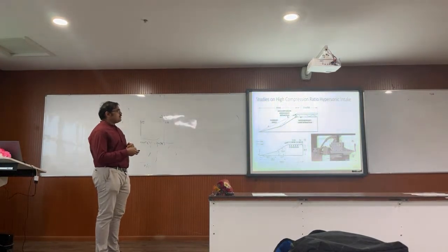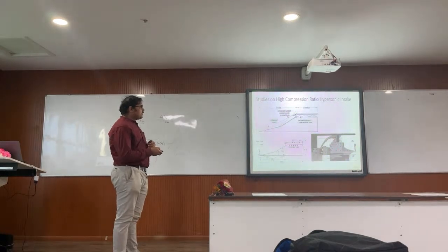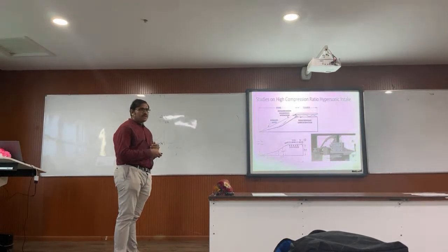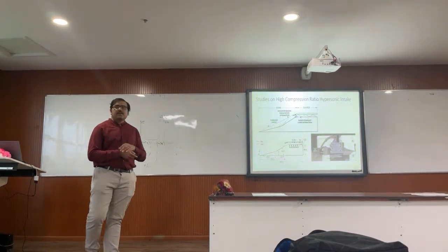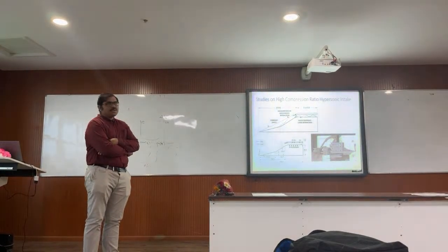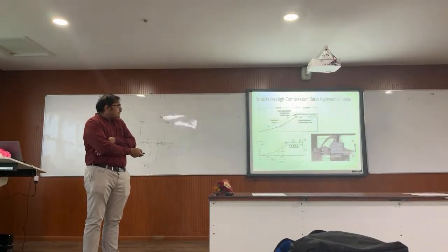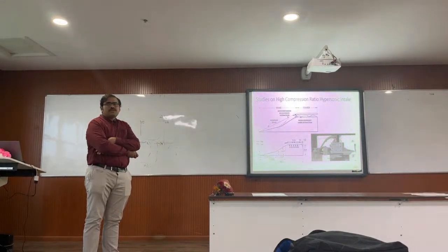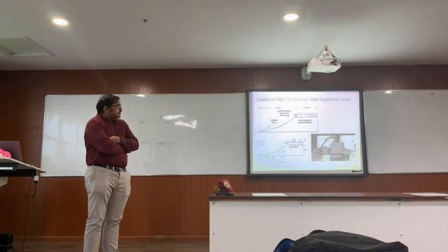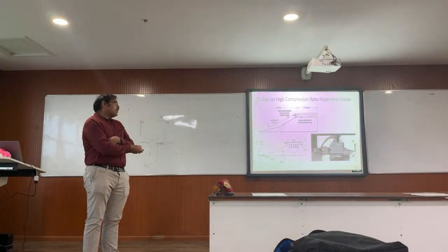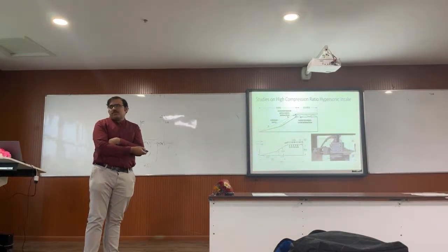We have a modular setup. Modular in the sense that this can actually move. Both the cowl can move as well as the flap can move. And these experiments are conducted in the hypersonic wind tunnel at the Indian Institute of Science. So we can actually move these flaps and cowls during the test time of the wind tunnel itself. That is called a movable flap and movable cowl system. So we have runs in which we might keep the flaps at a certain angle and see what happens to the flow, or we can move it during the experiment.